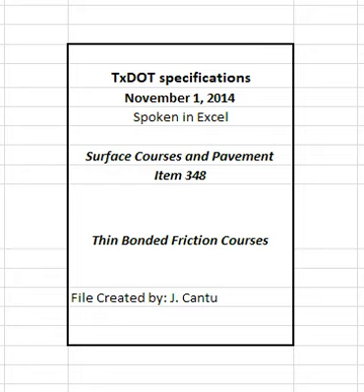Record and electronically submit all test results and pertinent information on department-provided templates. Subsequent sublots placed after test results are available to the contractor, which require suspension of operations, may be considered unauthorized work. Unauthorized work will be accepted or rejected at the discretion of the engineer in accordance with Article 5.3, Conformity with Plans, Specifications, and Special Provisions.